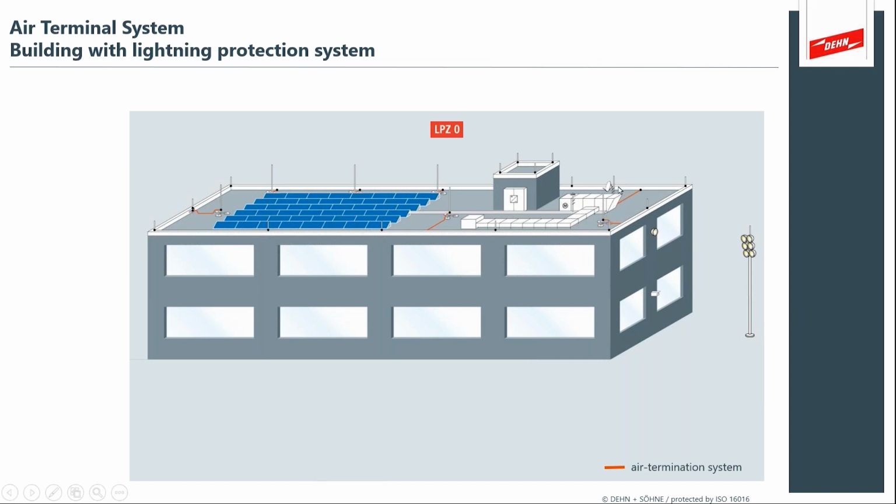Maybe it's antennas, like you see here, there's a small antenna, or maybe it's the chiller on the top of your roof, think of a data center that's covered with chillers to keep the important computer equipment protected from heat. So something like this is a really nice illustration that shows you attach the lightning protection terminals to the metal flashing of the roof, but you separate the air terminals from the very sensitive victims that you're actually trying to protect on your roof structure.